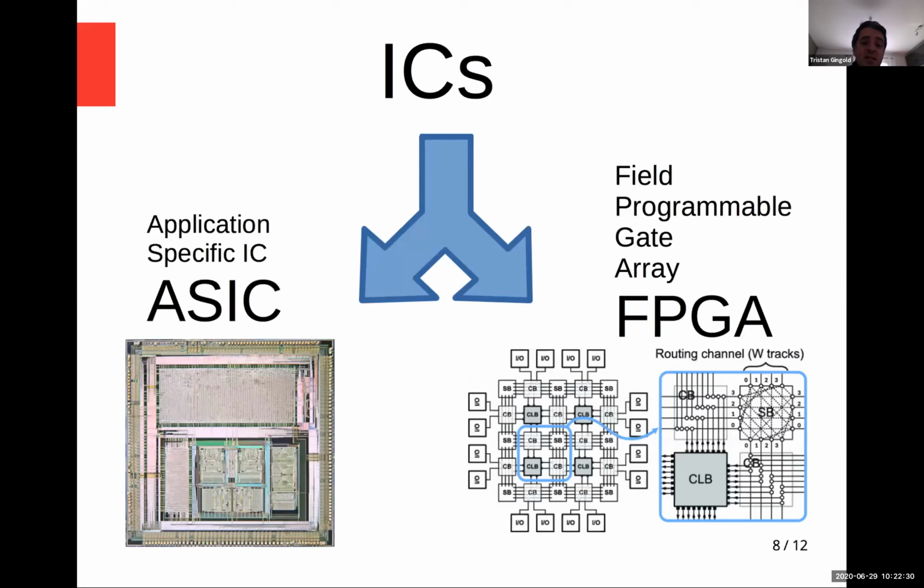The two main kinds of integrated circuit used for numeric applications are ASIC, in which case you have almost full control of what you can put into your circuit. But it also means that you have to create masks and go to a foundry. So it's quite a slow process, and also a very expensive one, because masks are very expensive and the process is also quite expensive.